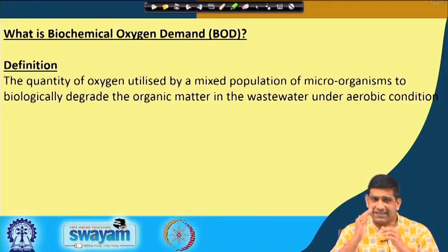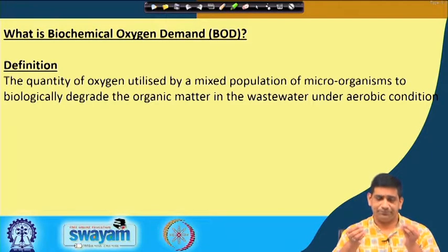As I keep on saying throughout this course, irrespective of what background you will be working in, water, resources, energy, all these things come into the picture in every domain, and so you need to have an understanding of the environmental issues associated with that. So, one of the important concepts is BOD. Now, what is this BOD? Biochemical oxygen demand. Now, why is it biochemical? Because it is the biological reaction plus the chemical reaction both together. So, that is why it is called biochemical oxygen demand.